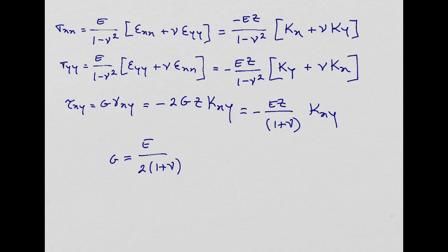All right. So we are making some progress. We started from simple deflection of the plate. We derived the displacement field. We derived then the strain field. And now, with Hooke's law, we get the stresses in the plate, which is great. But what we need to know now is how do these stresses evolve or progress from one point to another in the plate, right?